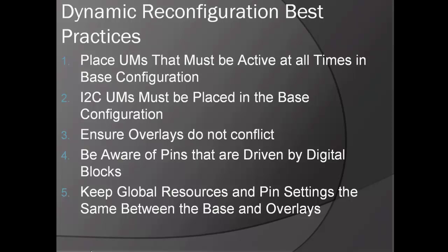Number 4, be aware of pins that are driven by digital blocks that are unloaded and loaded. For example, the TX pin of a UART. What state will it be in if there is no UART present to drive it? To ensure the state of the pin when the user module driving it is unloaded, use the digital output row lookup table to set the desired logic level.